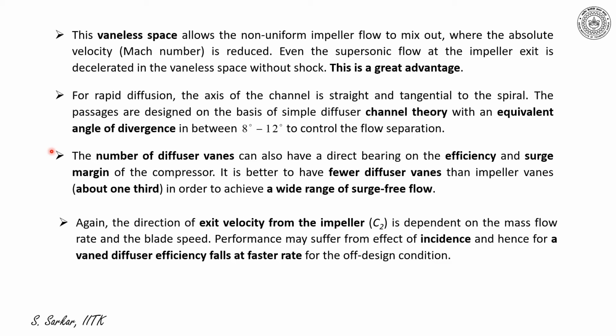Thus, it is better to have fewer diffuser vanes than impeller vanes. Roughly about 1/3 the number of vanes is recommended in order to achieve a wide range of surge-free flow.